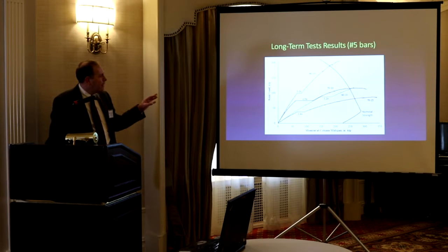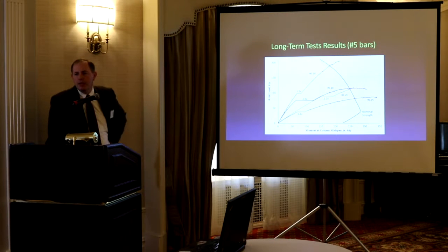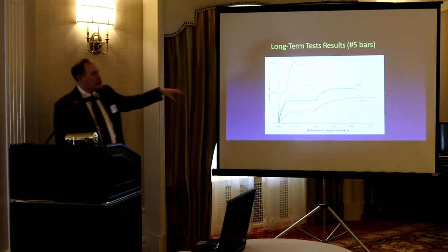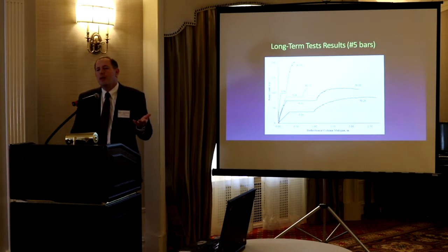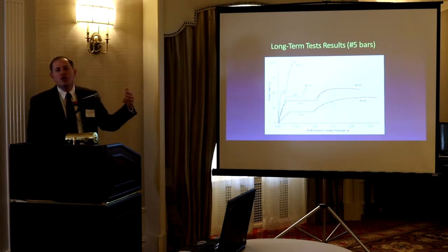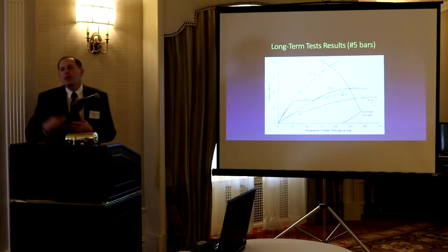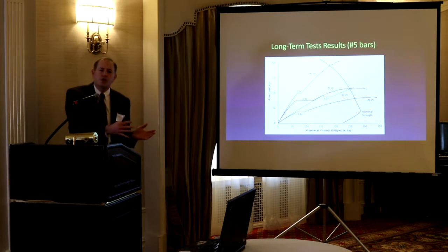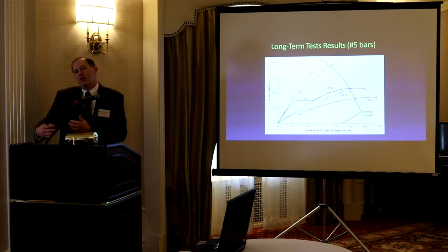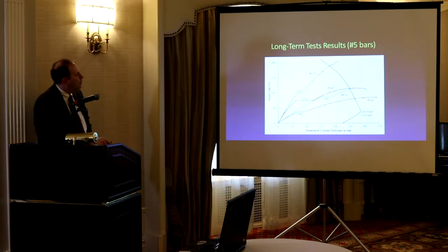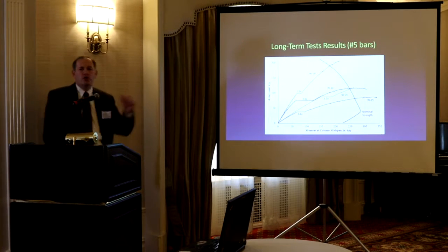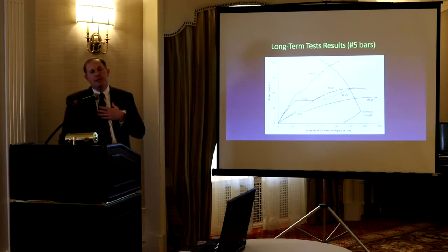So we take that, we can convert that to moment, so you can put it in a plot that you're used to seeing. Interestingly enough, the deflections look much higher, but when you convert to moment, it turns out that the jumps are not as significant. They're 1.2, and then there's 2 and 1.4. And so you'll see the moment change is not as large, because you have a first order deflection, and just look at the second order change, okay? So you'll see again, they all fail, even after sustained load, beyond the nominal strength, which is great. That's what we want to see.